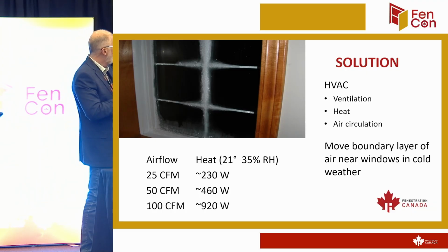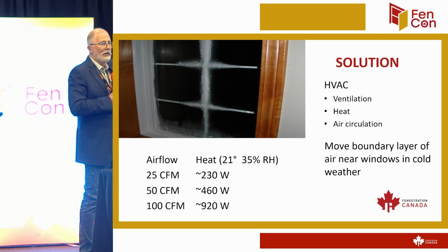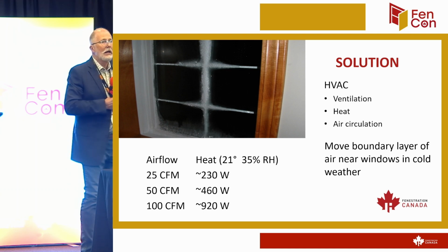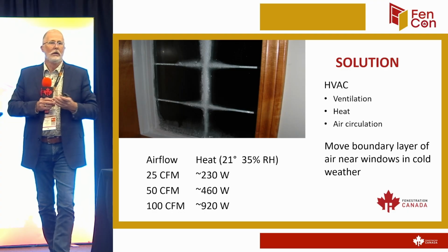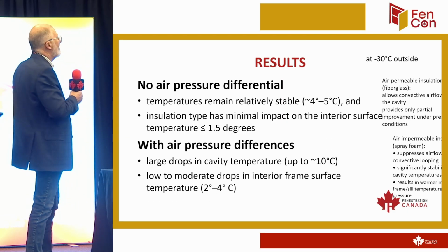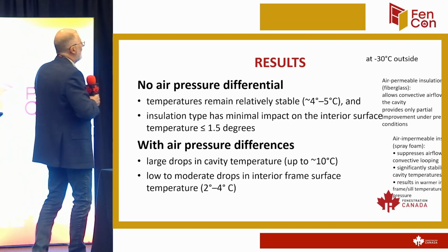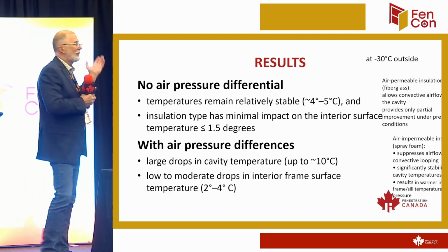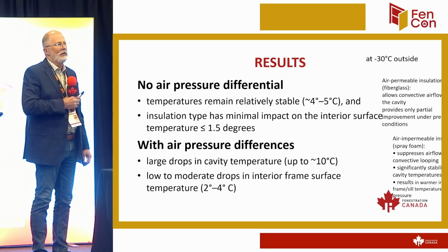5 CFM would give me 46 watts. That's more than enough to keep that vinyl window or a wood window from getting any kind of condensation or moisture on it. There's enough math; we know how this is working. So what were the results of the testing from NRC?